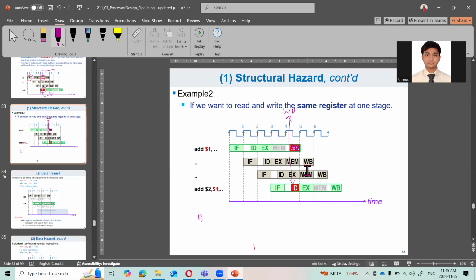Another nice thing of using the first half for write back is if you have written something which changes a register, then the ID uses the updated values. So that's a nice thing as well. The decoding uses the updated values because you wrote back just 1 nanosecond before, so you have the latest values, and for the instruction decode, you are now using the latest values.